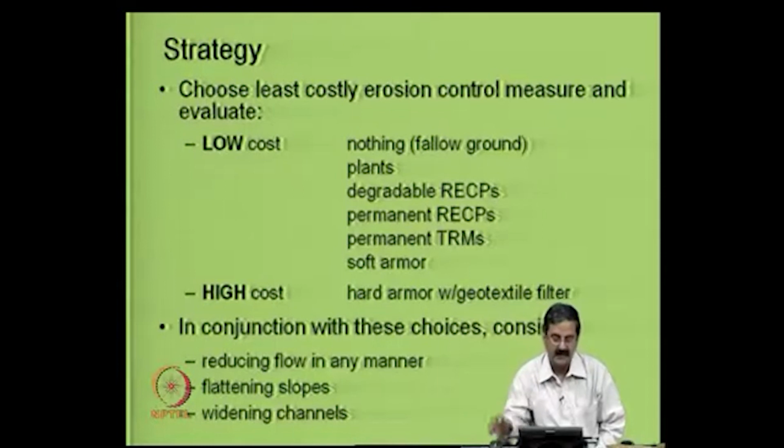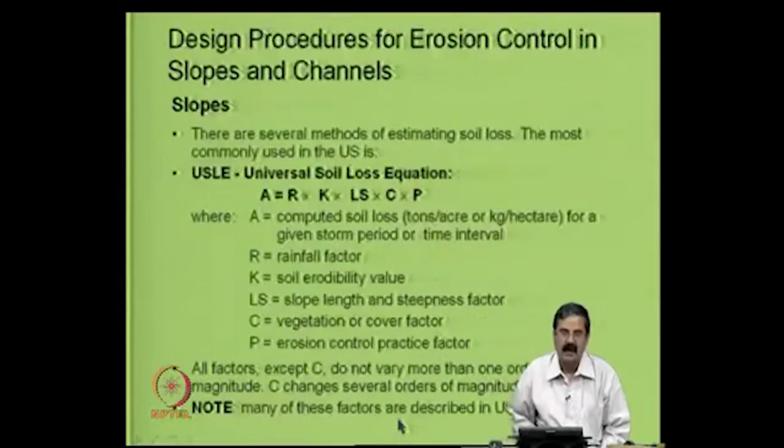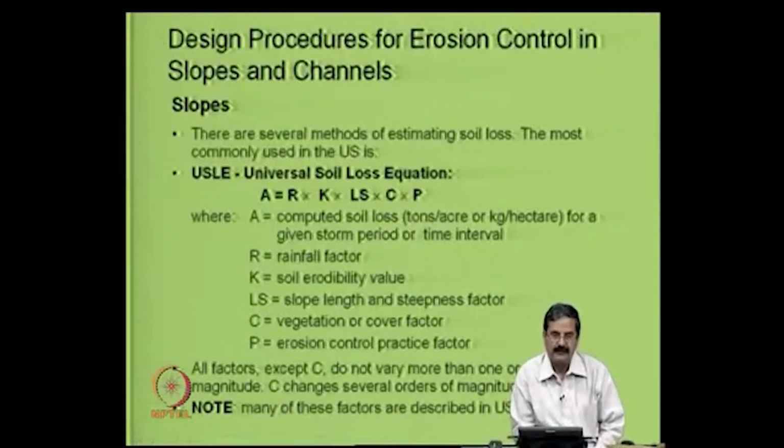Okay. Then sometimes in slopes, widening or flattening of the slope is another variable. Widening of the channels, because once they widen, the velocity decreases, and then it is nice. So, in fact, people try to use many concepts in these erosion control design procedures.